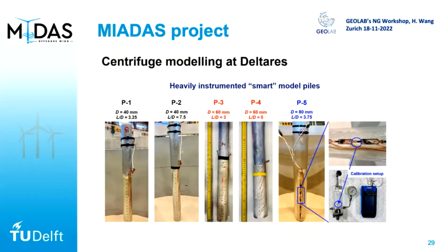And those were also hammered in, or were they wished in place? Yeah, for the test at the terrace, we do everything wished in place, because, first, we don't have a hammer at the terrace, but more importantly, we want to develop a numerical model to validate the centrifuge test, and it's better to have better control of the soil if we do it by wishing in place. If hammering becomes a little bit complicated, then that's the next step. Yeah, for the numerical to validate.